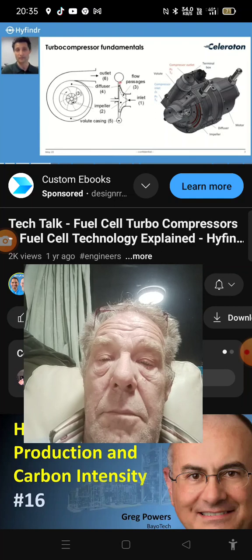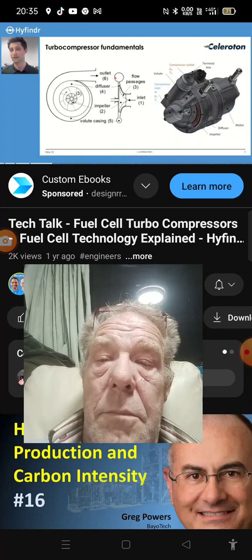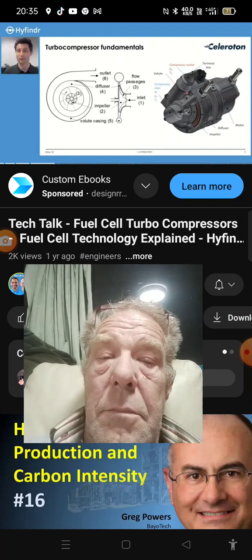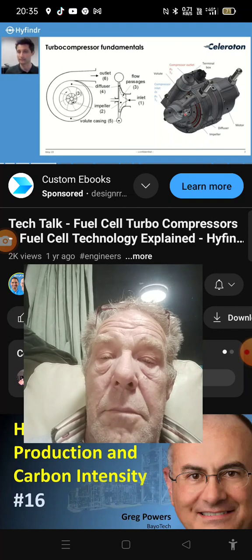After the diffuser we have, as I said, the so-called spiral casing or volute, where we further reduce the radial velocity and collect the flow towards the end application, which could, for instance, be a fuel cell stack. And maybe on the right-hand side, you can see one of our more recent designs that we have already presented at numerous fairs, where we can see how it looks in real life, which is a cut-through of one of our CAD designs.